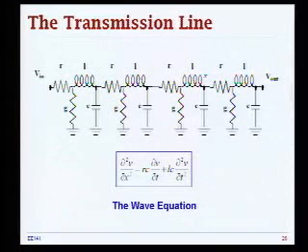Now, we have fundamentally a different concept over here that is called wave propagation. And again, you have seen this in your physics and EM classes. What goes on here is that in the wave mode, the energy gets exchanged between the electrical and magnetic fields, or equivalently energy gets exchanged between the capacitive and inductive modes in your network.